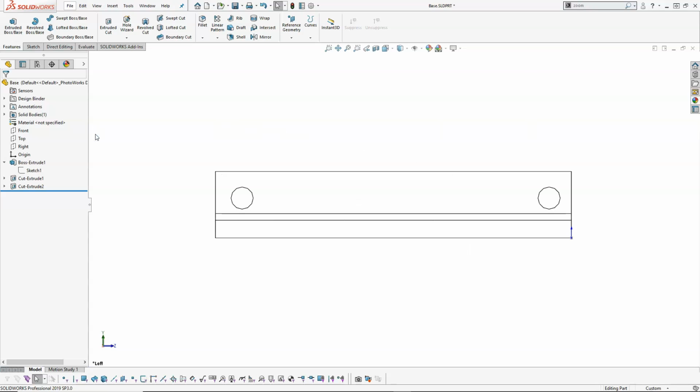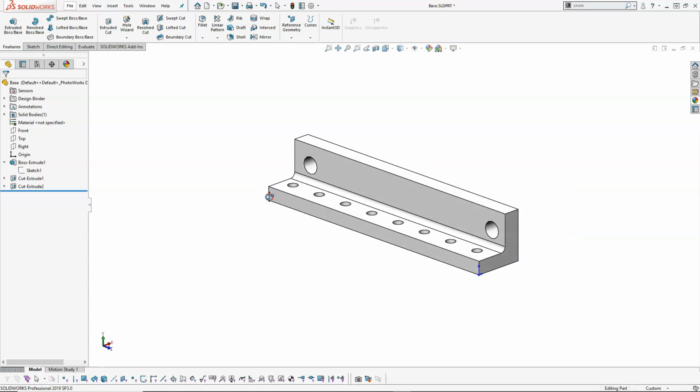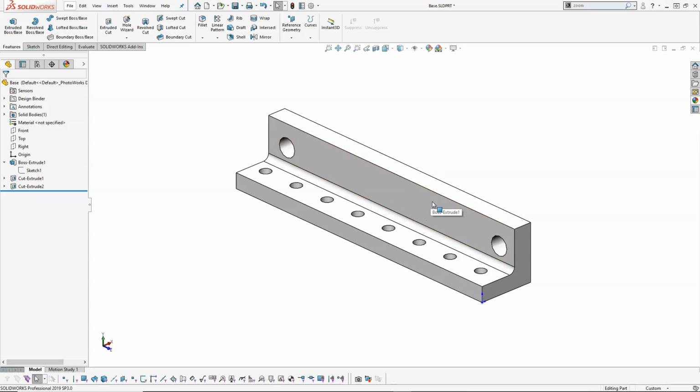Alright, so we have our shapes. That was control 1. Let's go control 3. And we'll rotate that around a little bit. Alright, we've given a radius of 12 in 2 places, but we're going to make the assumption that is a radius of 12 in 4 places. So I can left click to select an edge, hold down the control button, select another edge, and I did not get my additional items. Usually there's another one to pop up. Oh, I'm not in the fillet tool yet.